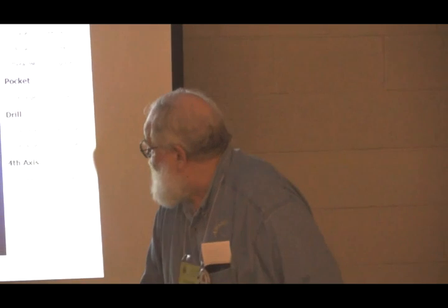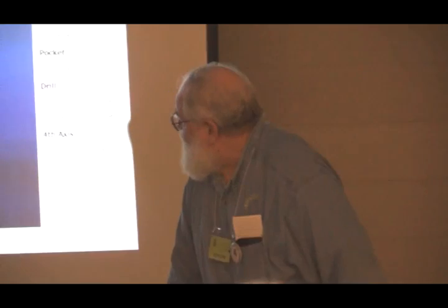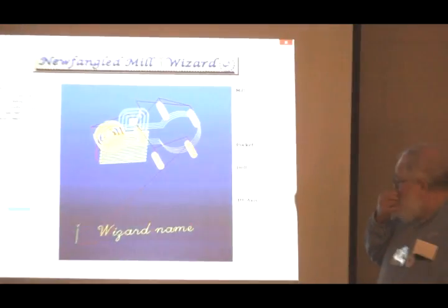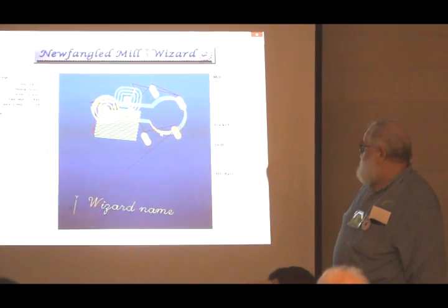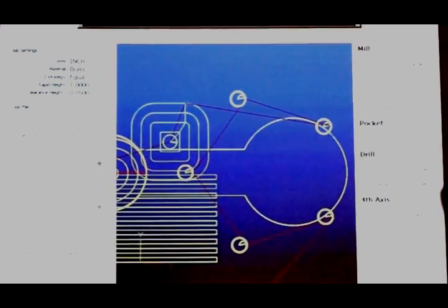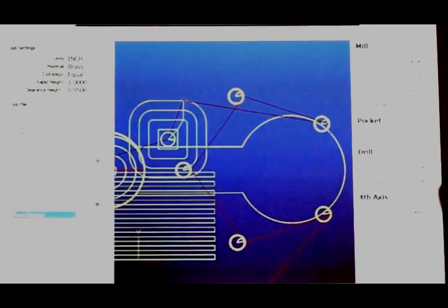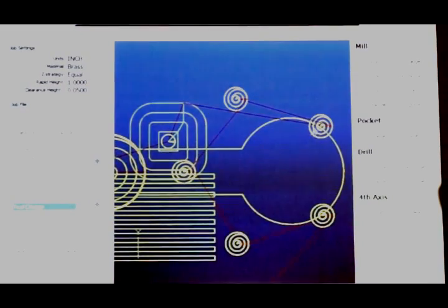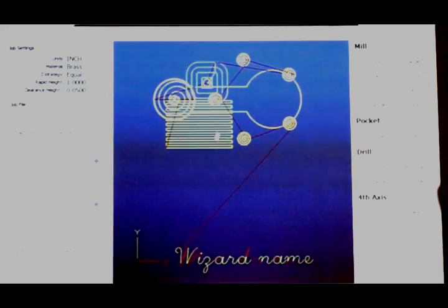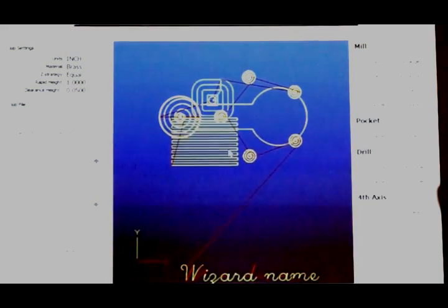So what are we doing here? Okay, here I've just added a 1/4-inch tool. This is neat. Now, we've got this whole circle we did over here. I'm going to shift it over like that. Now, when I click on this and I move it up, see how it instantly changed those? So it took the tool into account instantly. You didn't even have to recalculate. No, nothing. It's all on the fly. Everything happens now.